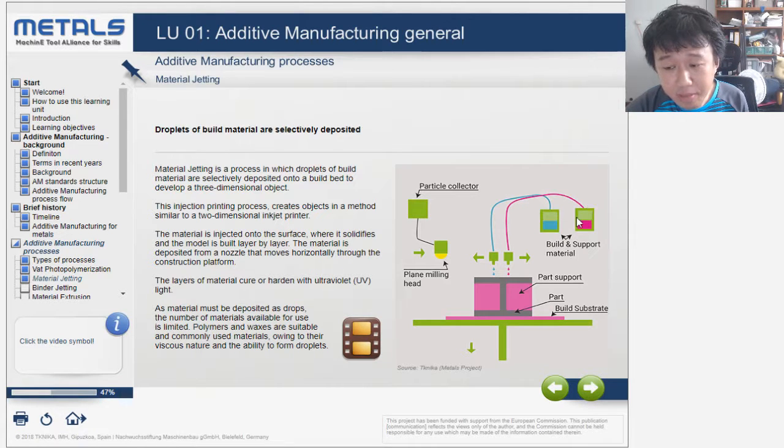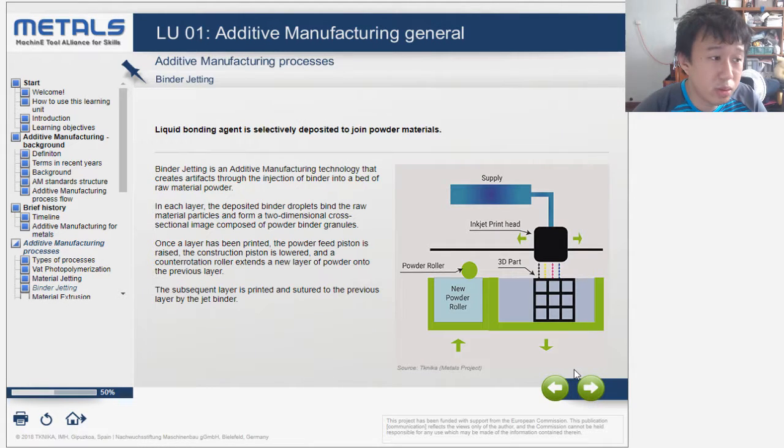So basically you are paying a lot for the build materials and the support materials, because there is a lot of tuning that you need to do, because if you simply put in your own materials, you actually clog up the nozzles and it'll cost a lot of money to repair or replace it. It might not be possible to repair it because all the nozzles are microns in size, so it's very difficult to unclog once it's clogged.